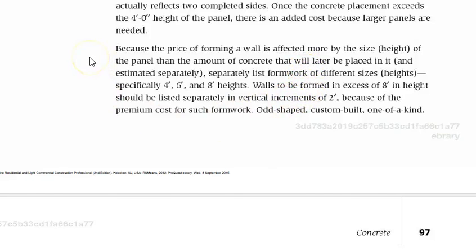And at that point, again, still concrete isn't the governing cost factor. It's that truck that carries the pump, because they're a very expensive piece of machine. You usually have to pay for a pump for at least 4 hours guaranteed, generally a day. And when you're talking about maybe $500 or $600 an hour or more a day of a truck for 8 hours, and if you only need it for an hour or two, you can see how the cost is going to run on you.